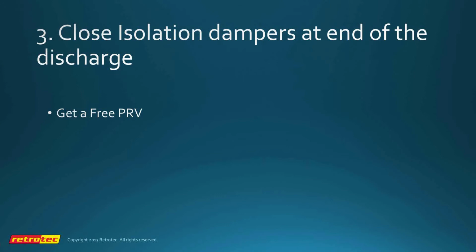Often what happens is that the HVAC system is often isolated with vents that close, and by simply changing the timing on the closure of these vents, we can provide a pressure relief vent through the existing HVAC ductwork. So essentially you get a free pressure relief vent by changing the timing of the closure of the vents in the HVAC system. And this can be measured with the door fan.